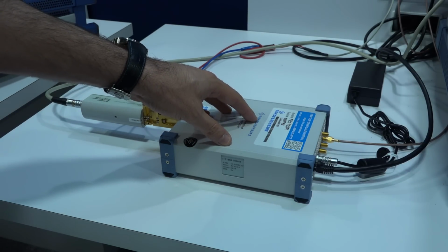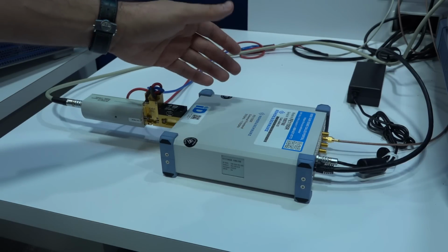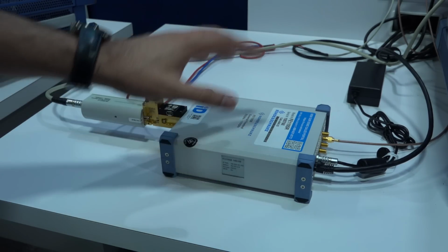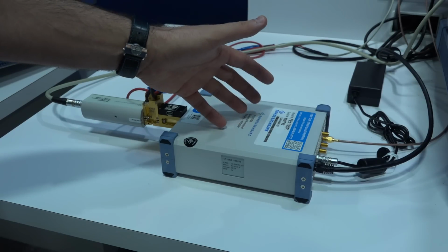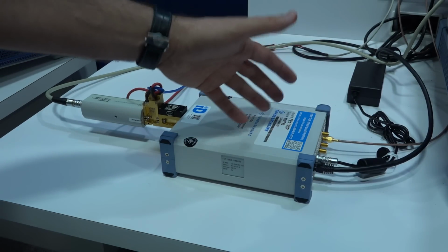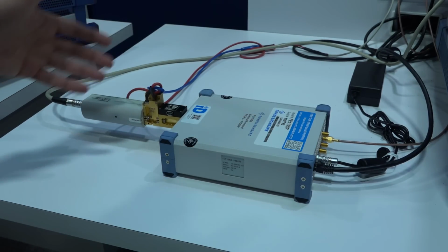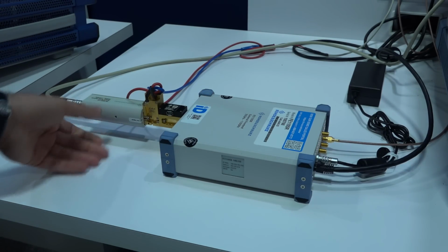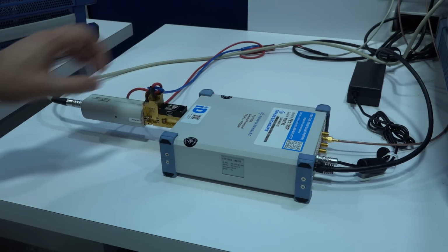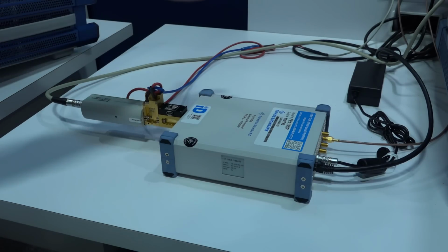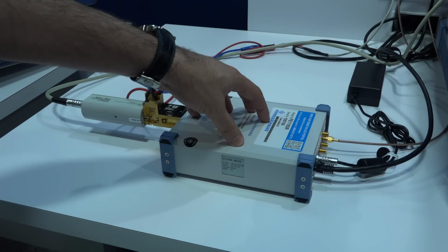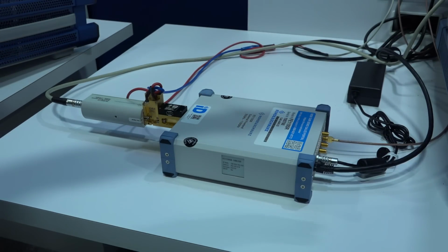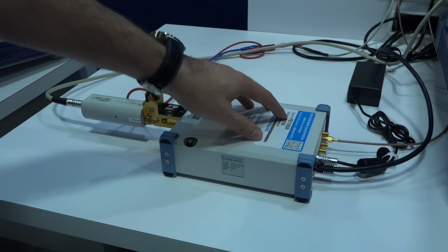And of course, you've seen the FE series frequency extenders on the channel before. I've done a review of the 110 to 170 gigahertz version of it. This is the FE110SR, which goes from 70 to 110 gigahertz. Now, all of these instruments have a built-in synthesizer, and the synthesizer is sufficiently low phase noise that you can actually perform direct noise figure measurement on this. And you have a smart noise source over here, they have a filter in the front, and they have this device that they want to measure a noise figure of. And you can actually do it directly on this on an external head connected to the FSW.